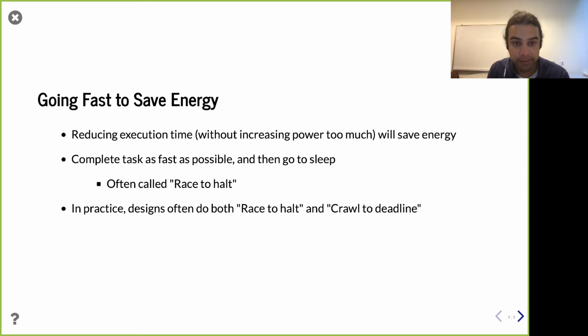So at the circuit level, static power happens from things like leakage, where your transistors aren't perfect, and so even if they aren't changing, some amount of power is getting dumped to ground. But even architecturally, there's some amount of power burn, what's called static power. It's just things that are always there, right? Just to keep your platform on, there's a certain amount of stuff that's always running, and that's always burning power.